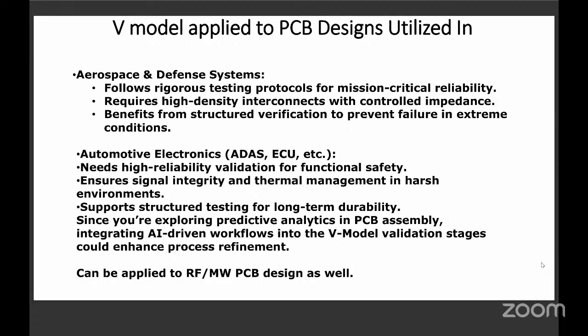It becomes an absolute necessity in Ultra HDI because of the features what you told in the beginning: a finer trace width and gap, very well defined via structures, and signal integrity and power integrity challenges. And there is what is called the structural integrity. It is very much important. That's why the V model comes into a key role. And V models are already integrated into CAD systems and CAM systems.